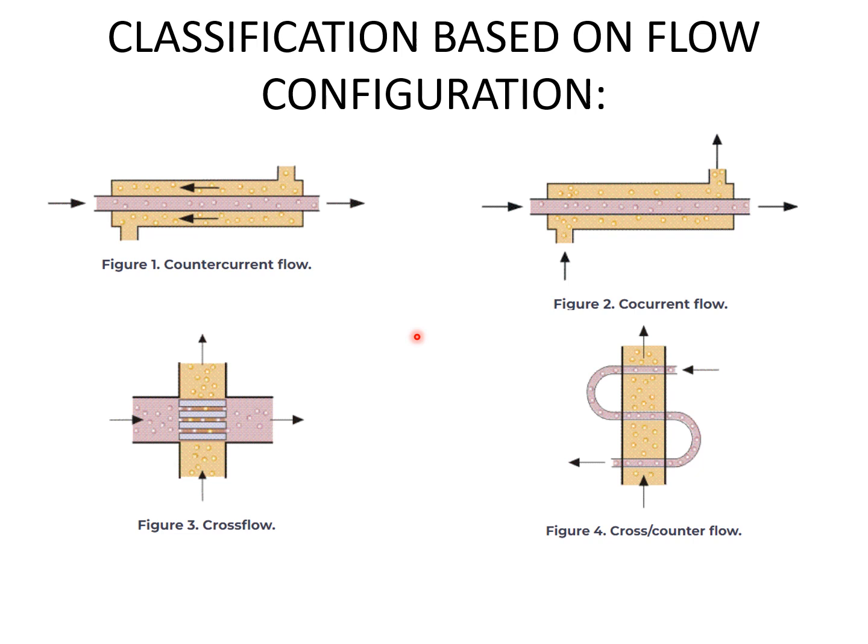If it is a counter-current flow, the efficiency of the exchanger will be very high, very good. But in case of co-current flow, your efficiency will come down. So when we design an exchanger, we always try to have a counter-current flow. That is the opposite: for example, the heating medium goes here and the cooling medium goes the other way. Co-current means both liquids have a parallel direction of flow.